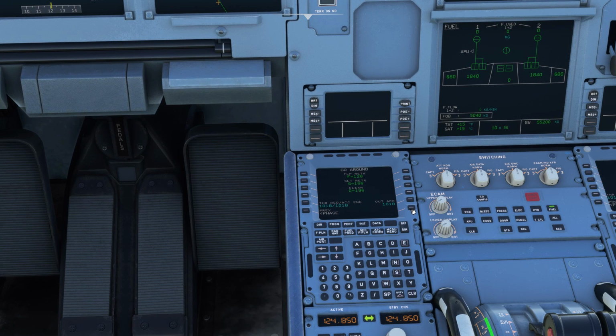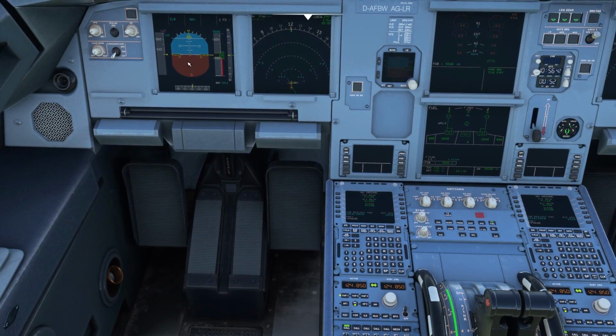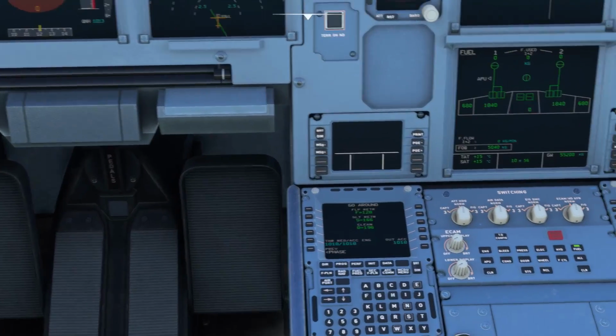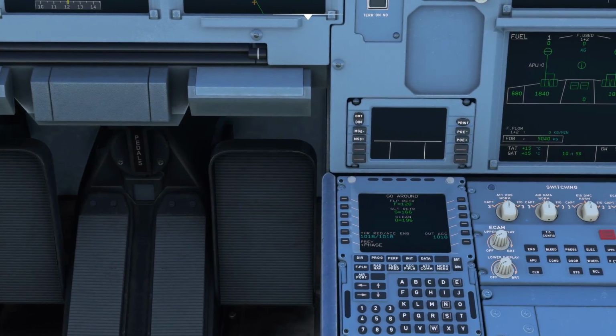Now we're going to go to the next phase, and this is the final phase. Okay. Now this normally has a standard setting in there in the thrust reduction. This is all you can really change here. But basically, this is the go-around phase of the MCDU perf page. Now, all this would mean is that at 1,018 feet above the runway, I'd be telling you to basically go for a thrust reduction. Okay, so that's where it'd be like lever climb. Okay, so obviously in the event of a go around, you'd set the throttle to take off go round, and then this will kick in.